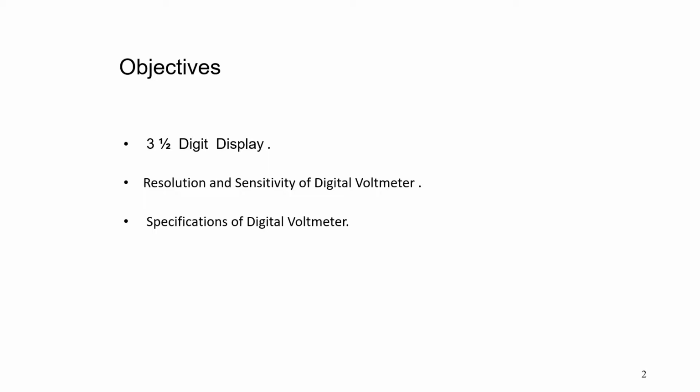At the beginning of each measurement, a start pulse is applied to the start-stop multivibrator. This sets 1 in the MSB of the control register and zeros in all the other, less significant bits.